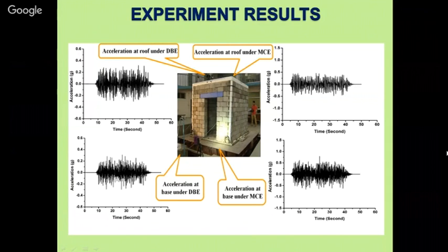And further, this interlinking viscoelastic link element is very cheap, because one element costs less than 25 paisa or so. This steel plate is also of very cheap cost, because it is very light in weight. If you apply any earthquake features, like vertical reinforcement, horizontal reinforcement, or providing more cement mortar, you are adding mass to the building.